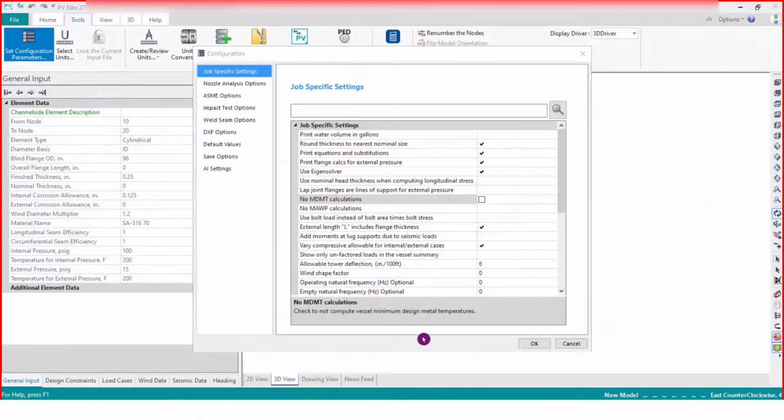So because of this, any temperature there is termed as MDMT. Based upon the geometry, the code has also given that a particular material can sustain certain temperatures. The code, based upon the geometry selected, thickness selected and material of construction, will tell us; rather, the software also has the option. The software will tell us whatever geometry you have selected, along with the MOC and the thicknesses, can be used till what temperature.